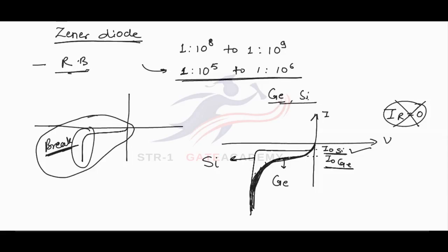In reverse bias, in this particular region, this diode is not operating, only a reverse saturation current is flowing through diode, and now the current is increasing, means diode is entering into breakdown. This breakdown we can see is gradual. But if we take silicon diode, then in the characteristics I have shown that this breakdown is sudden.